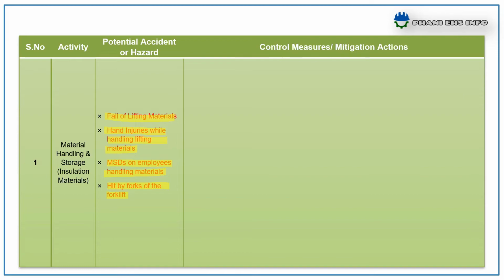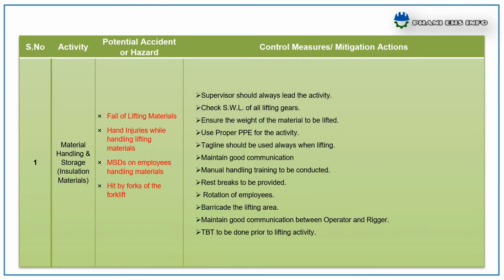To avoid these hazards, the control measures are: supervisor should always lead the activity, check safe working load of all lifting gears, ensure the weight of the material to be lifted, use proper personal protective equipment for the activity. Tagline should be used always when lifting.